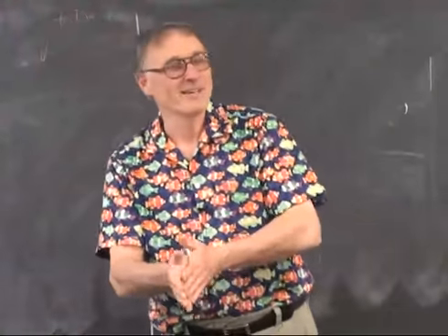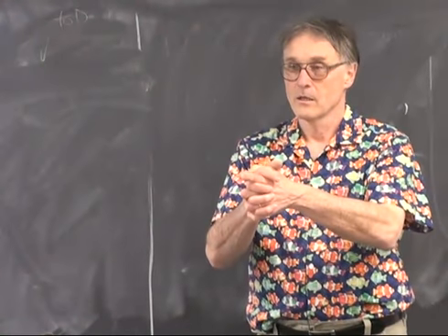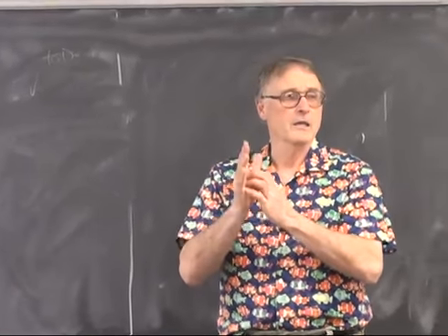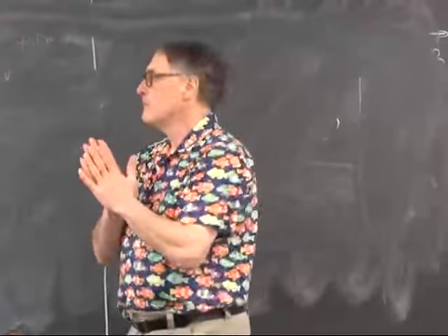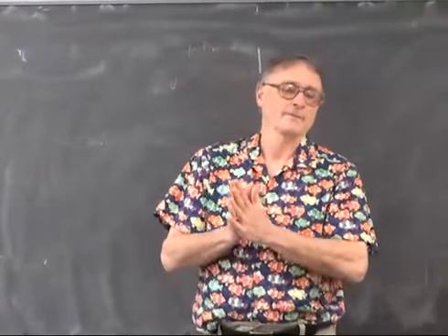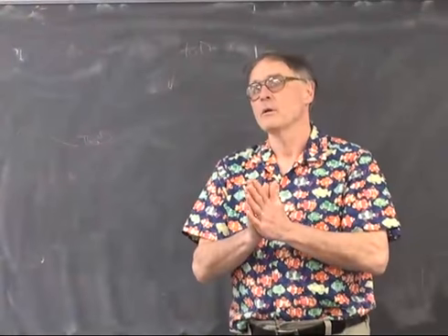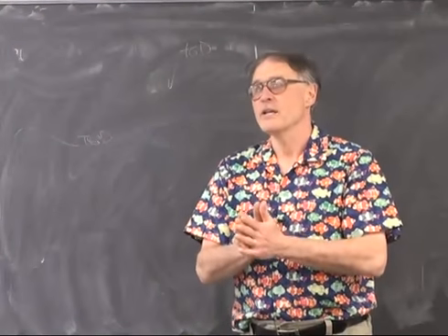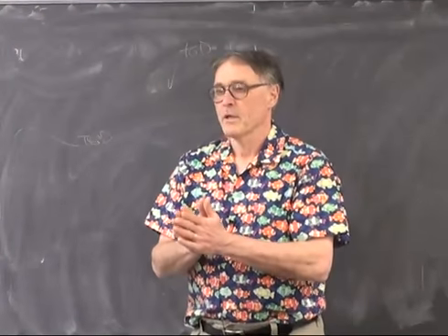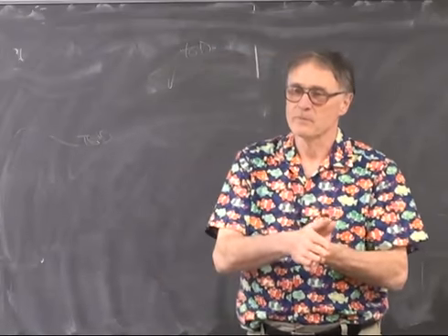Any questions about Lab 1? Type volatile. What does type volatile do? Type volatile tells the compiler that the variable can change without warning. It's used for communication between interrupts and main.